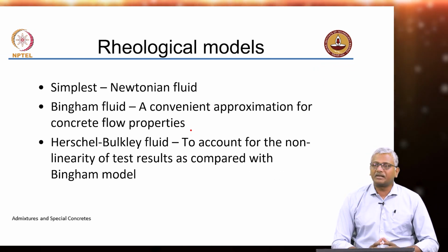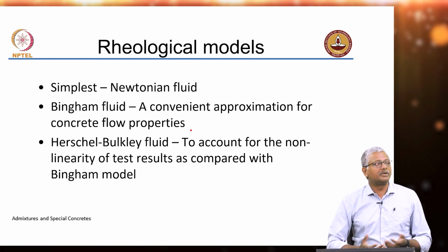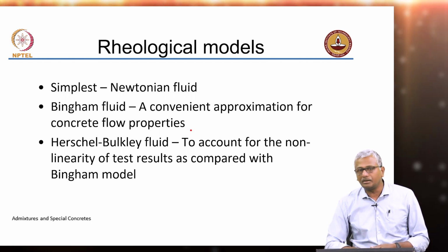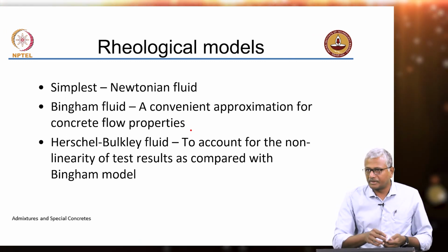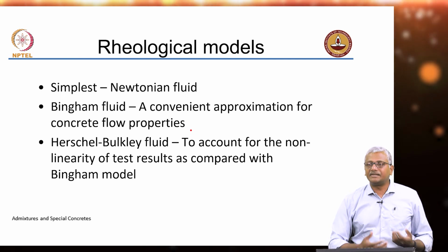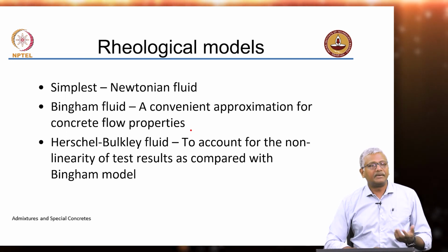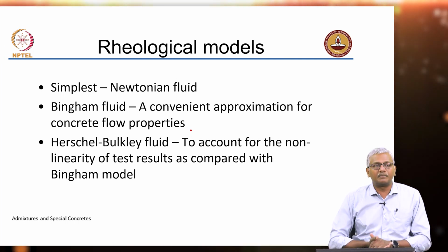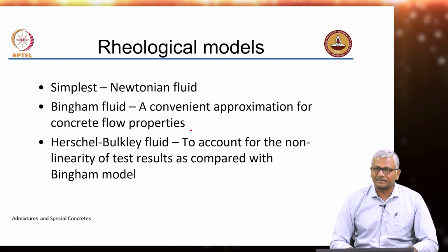So most materials are described by their rheological behavior, and this behavior can be captured with the help of simple models. The Newtonian fluid model is the simplest model, which applies to water or oil, right? As soon as you start shearing the plates, the water will flow. Any shear that is applied will cause the water to flow, right? When the fluid has an internal buildup that needs to be overcome to cause the material to flow, we call those Bingham fluids. So you have some sort of an internal cohesion that needs to be overcome to cause the flow to happen, just similar to your behavior of granular materials versus clay, right?